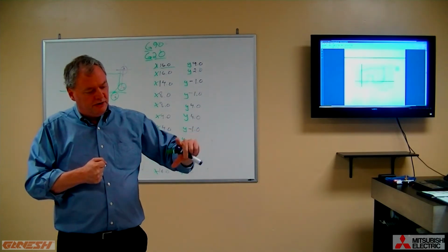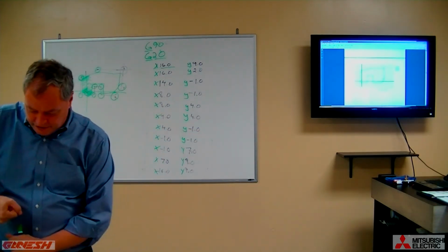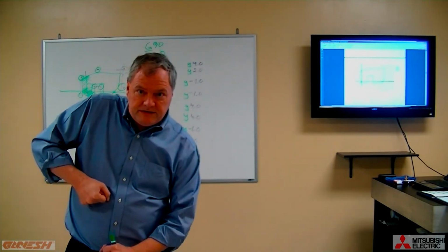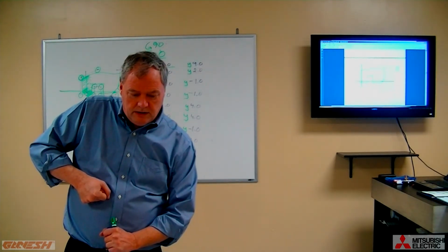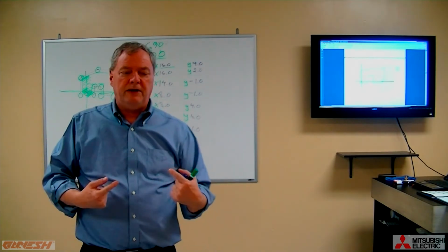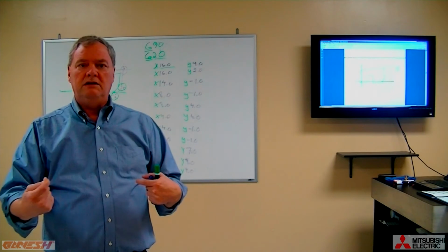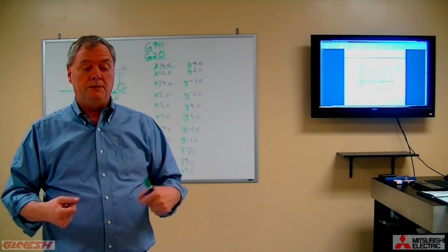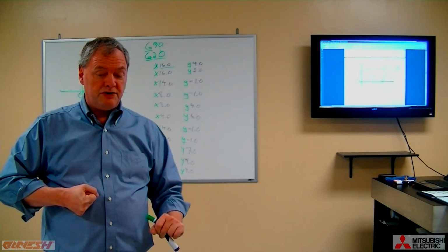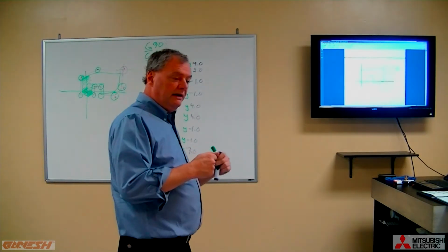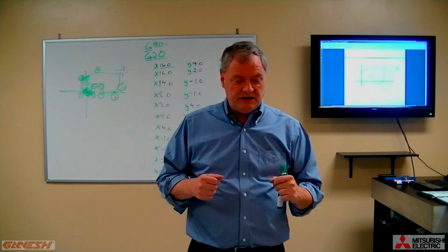Take that big drill into a piece of wood, you're going to do it by hand, you're going to feed it slowly. And as you feed it slowly, you'll see it's cutting more effectively. So by slowing down the speed of the spindle or the tool, slowing down the pressure that you're applying, it all comes into play and all has to be considered.